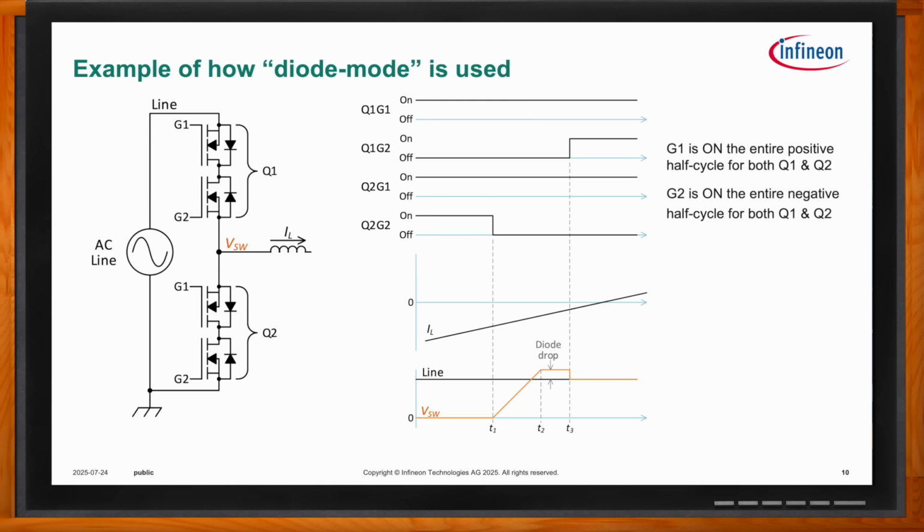So, Eric, it looks like the diode mode prevents the situation of an unclamped inductive load, which could result in an overvoltage during dead time. Yeah, that's exactly what we're doing. If you go back and read the EPC paper, they do actually predictively know when they should switch exactly at the correct time, so they never go into diode conduction mode. But for many applications, that's a pretty significant burden of measurement and control, and usually the dead time is fixed, independent of the current.